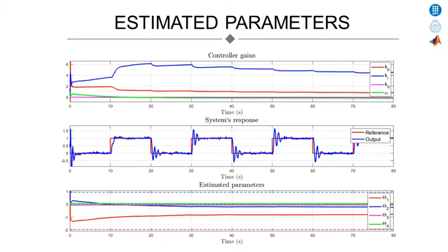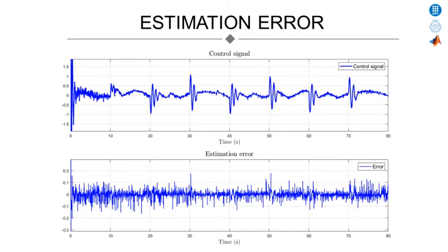These images show the experiment done in the video. As we can see, at first, the parameters vary a bit, but finally they settle at a constant value. This makes the output look different on the first pulses compared with the final ones. As we can see, the estimation error, although quite noisy, and even though the parameters don't converge to their real values, always tends to 0. This is because the recursive least squares algorithm tries to minimize the error between the real output and the estimated one. This doesn't mean the parameters will tend to their real values, as the regression vector can have other parameter values and still make this error tend to 0.